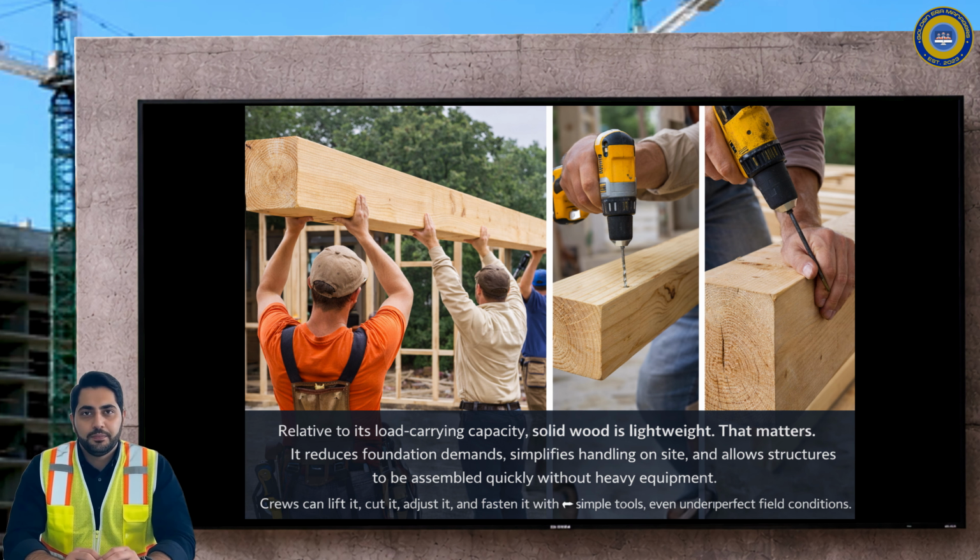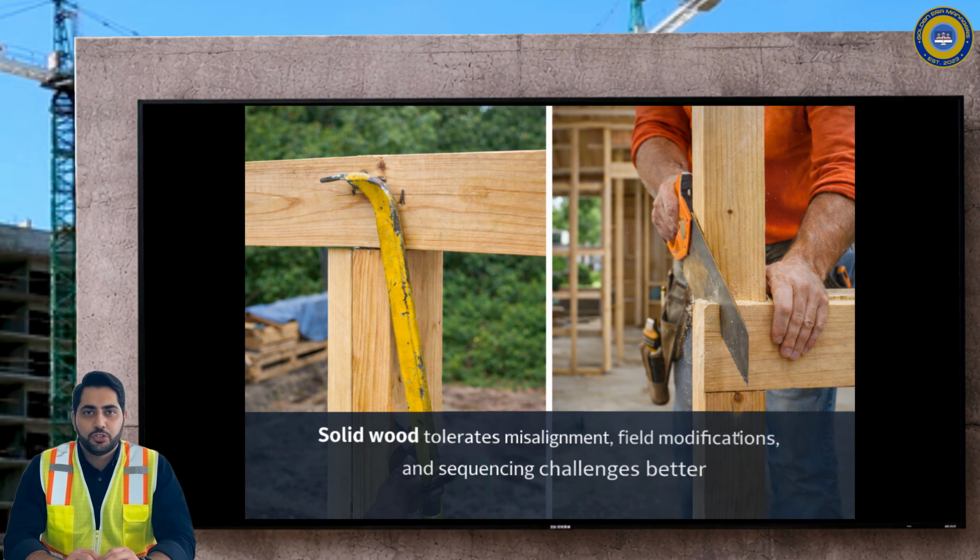That matters. It reduces foundation demands, simplifies handling on site, and allows structures to be assembled quickly without heavy equipment. Crews can lift it, cut it, adjust it, and fasten it with simple tools, even under imperfect field conditions. Solid wood is also forgiving during construction. It tolerates minor misalignments, field modifications, and sequencing challenges better than many alternative materials. When conditions aren't ideal, which is almost always, solid wood absorbs error instead of magnifying it.